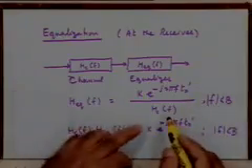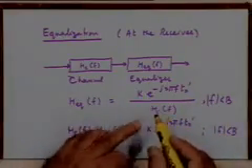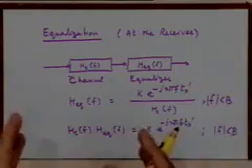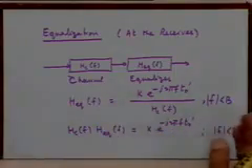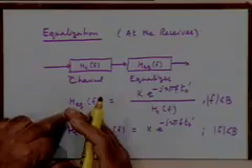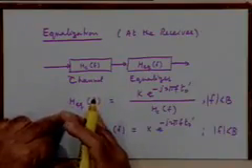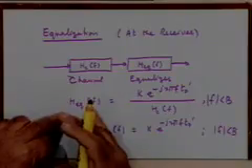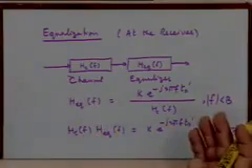Right? Suppose the channel H_c(f) has a null in the range of some frequency components within the message bandwidth of interest. Over a few frequencies, or in the neighborhood of some frequencies, the channel exhibits very deep attenuation, very large attenuation. Suppose it happens. It can happen, right? Then what will be the required equalizer characteristics at those frequencies? Very large amplification at those frequencies. And if you implement that, you can do that.